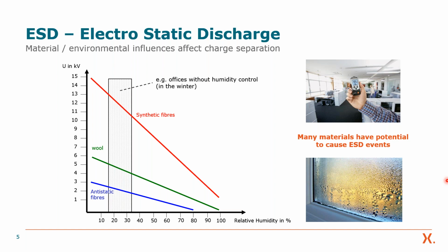But what is very interesting is that the more dry the air is, the more electric charge can accumulate. And this actually is very inconvenient because, for instance, in production, you want to have humidity as low as possible in order to avoid corrosion. But in effect, the potential of the ESD is very high. So the threat of ESD, of this malfunction and damages, exists everywhere.